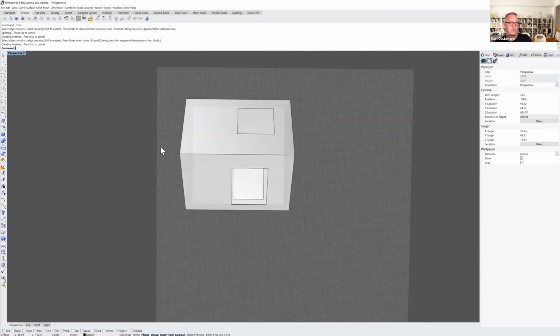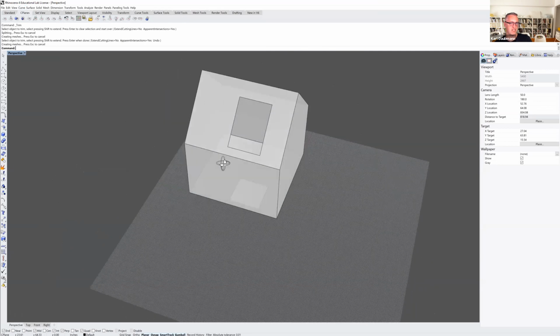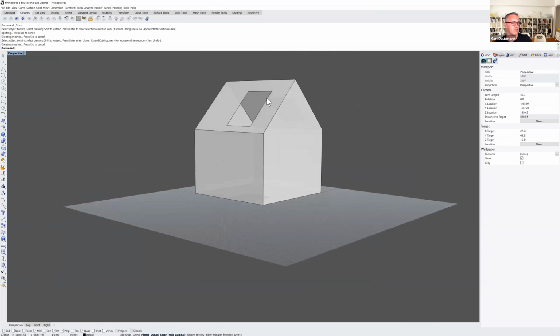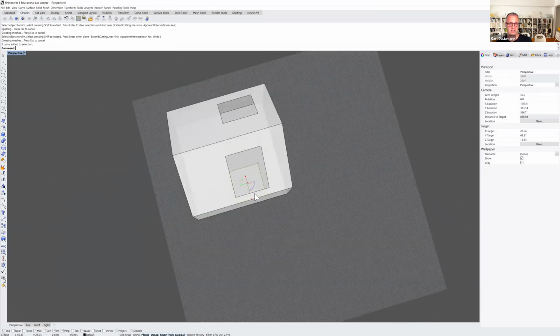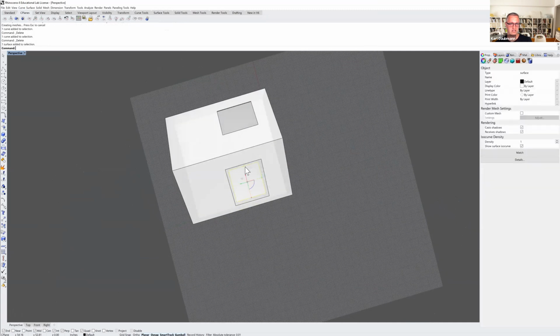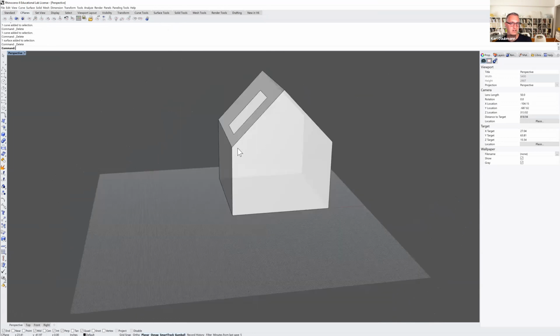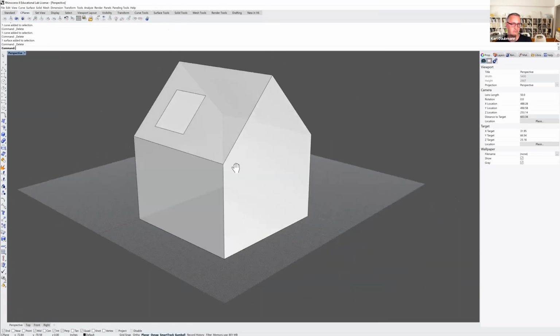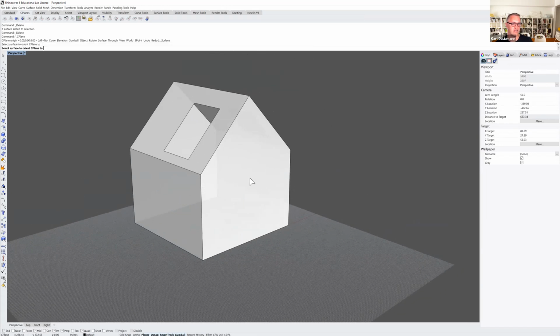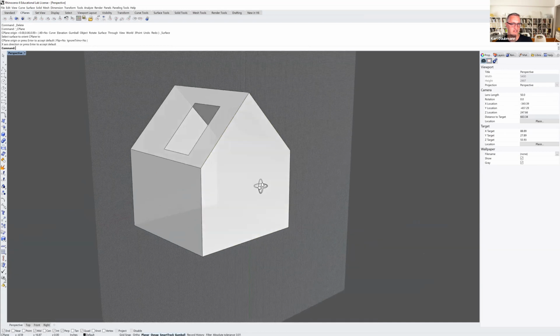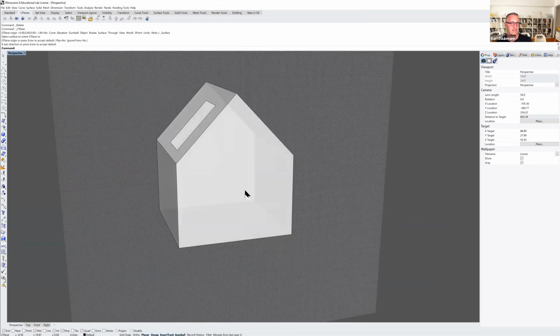This is a 4 foot by 4 foot cut opening in plan, but it's not 4 foot by 4 foot when it hits that surface, just given the projection and given those things. And so when you want to draw on a specific surface, let's draw something on this face. I can set the C-plane to that face and then hit enter. Now the construction plane's there.